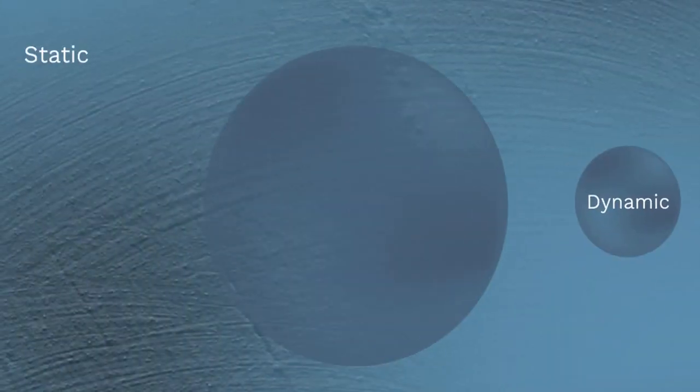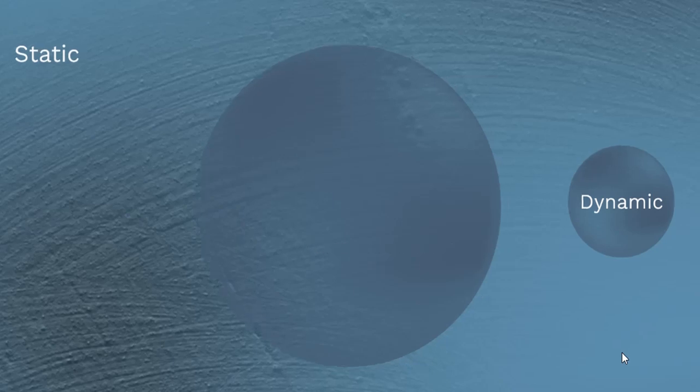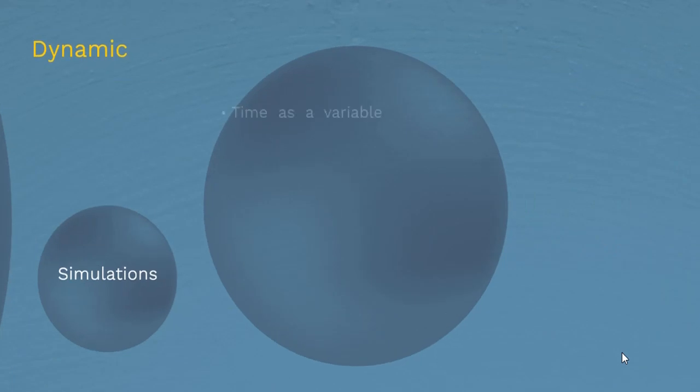This simulation can be done in either of two ways, static or dynamic. The static simulations used in process design simulate the process at steady state conditions, usually at the design operating conditions, and time is not a variable in the static method, whereas the dynamic models consider time as a variable and simulate the process over a period of time.